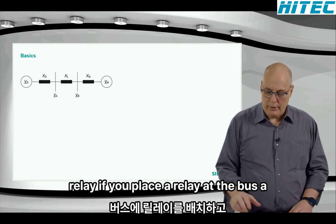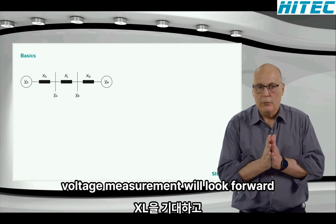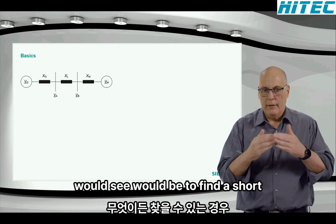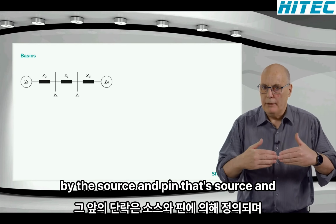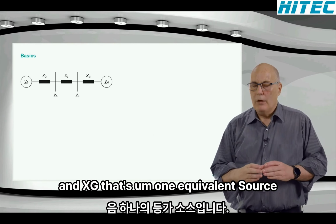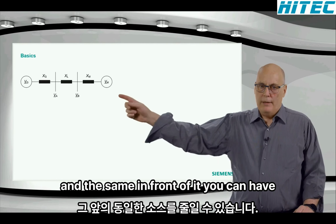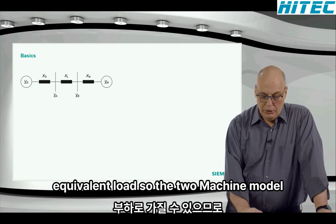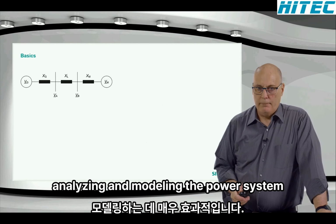If you place a relay at bus A over here, that relay with its current and voltage measurement will look forward towards the XL, and whatever that relay would see, a short circuit in front of it, would be defined by the source impedance. That source impedance is all the generation behind it. That would be the VG and XG, our one equivalent source. You can reduce the entire source of that one relay to one equivalent generation. And the same in front of it, you can have the ZL and the remote bus bar, one equivalent load. So the two-machine model is very, very effective in analyzing and modeling the power system.